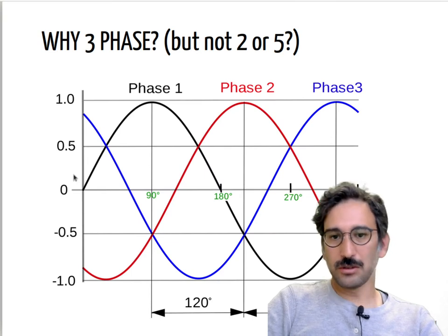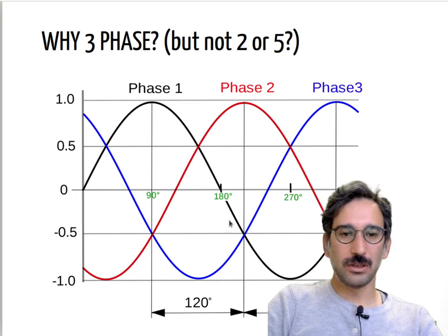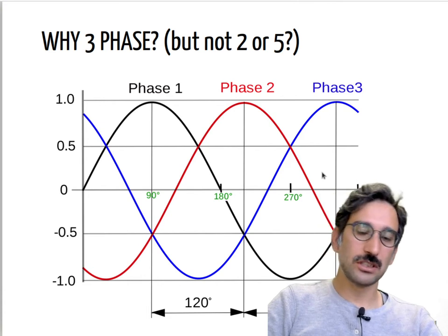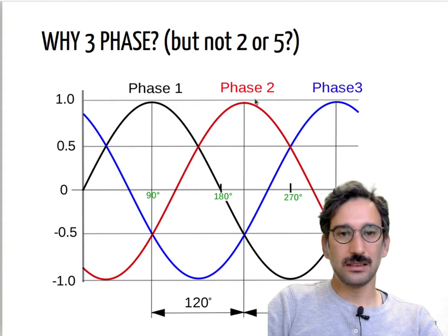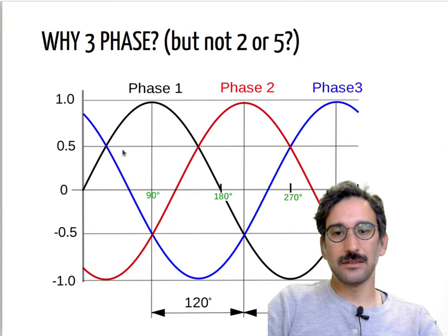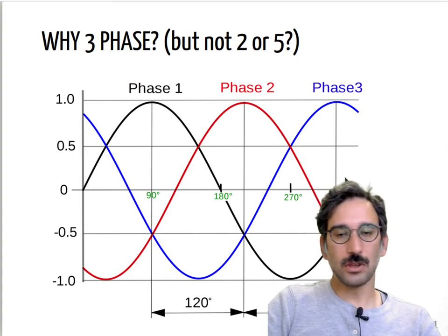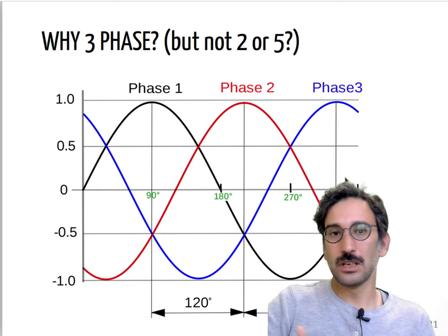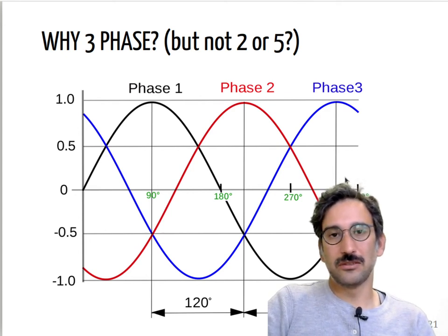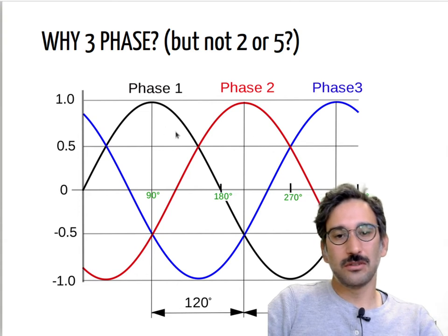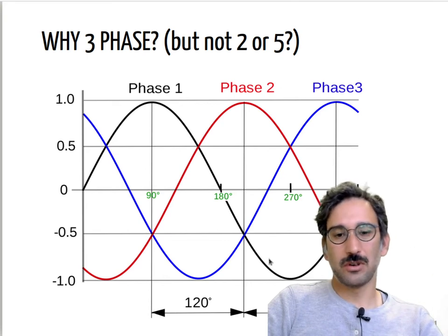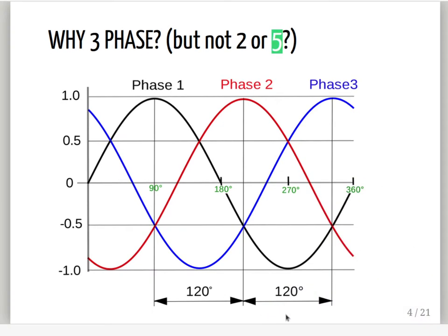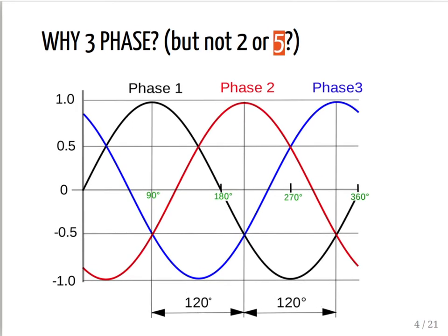So on a normal 3-phase system, again, what we know is all those voltages or currents, whatever, are balanced. So they have equal magnitudes, they have the same frequency. Okay, it doesn't have to be always 50 Hertz in a motor drive. It can be a different frequency, but the frequencies of these 3 phases will be equal, and they will be 120 degrees apart from each other. So there will be a phase difference of 120 degrees between these ones.